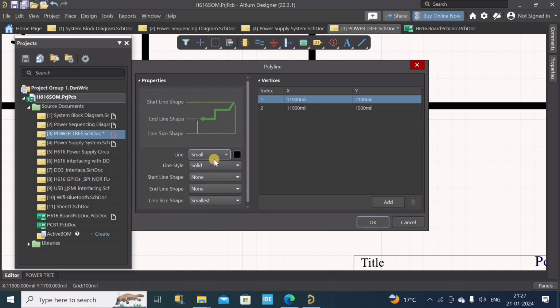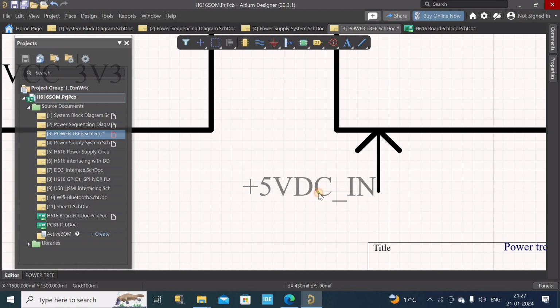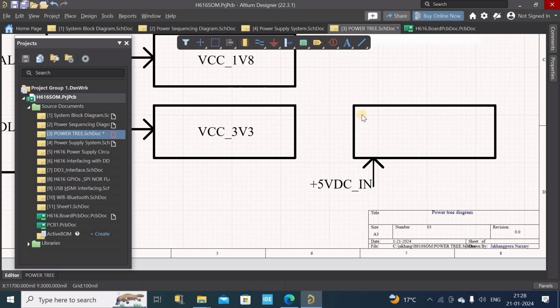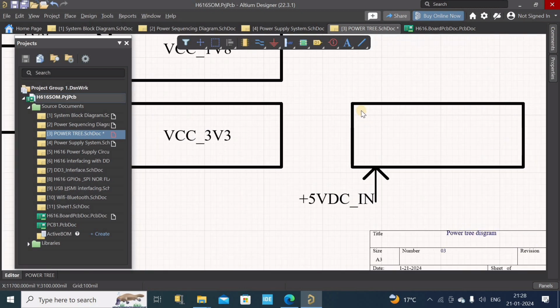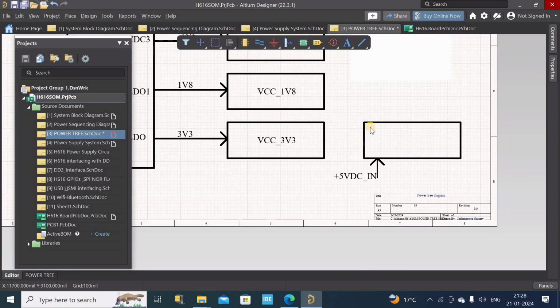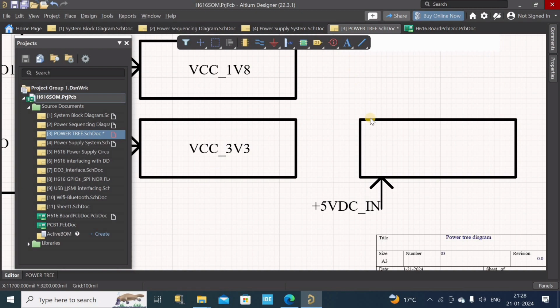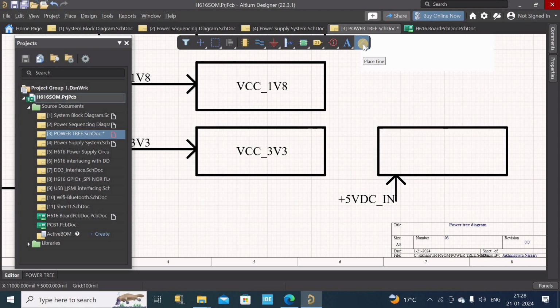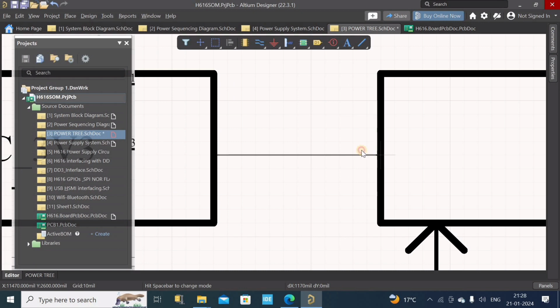So in order to power it up, we need an external 5 volt DC voltage. Okay, and we have one pin enable, in order to initiate its operations, whatever operations it has to perform, like voltage conversion. So to do that, we have to input this 3.3 volt for enabling this.